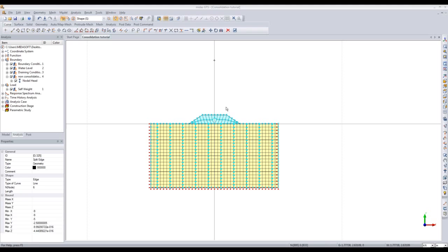Okay, so just to try to clarify, over here is our origin, right in the center. This would be our global coordinate system, and here's 0, and here's like 10 meters. So once you input 10 as your nodal head, the program will recognize that this area here is fully saturated. Does that make sense?